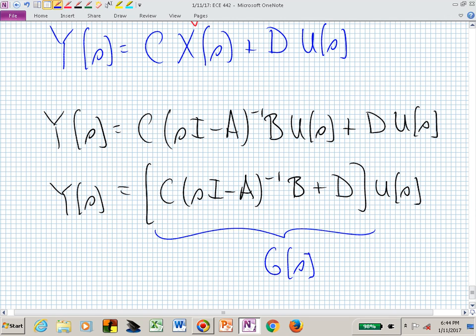And we've now gone full circle, or we've actually been able to catch our tail, and we now have an expression for our transfer function, capital G of s, in terms of our state space representation, which was in terms of these matrices, A, B, C, and D. And that's our cheer. We have our cheer, one of those, I think. Did you forget that over the long break? That break wasn't that long. It's now C times the quantity sI minus A inverse B plus D.